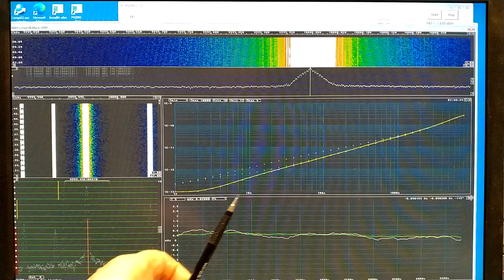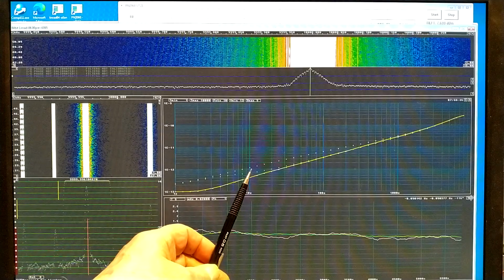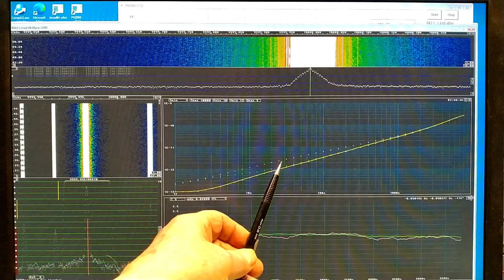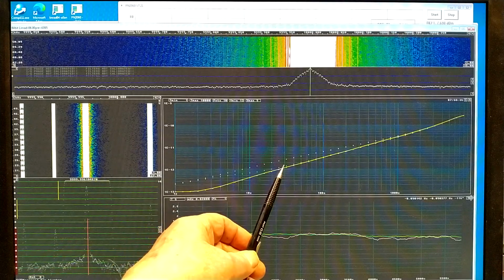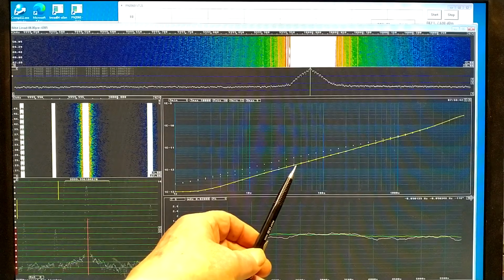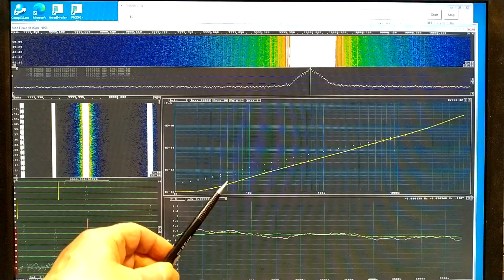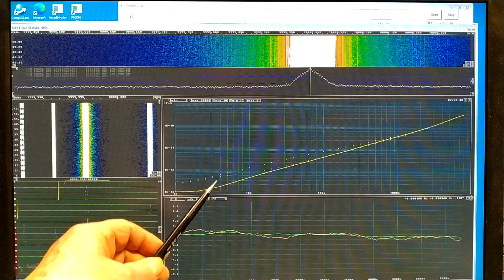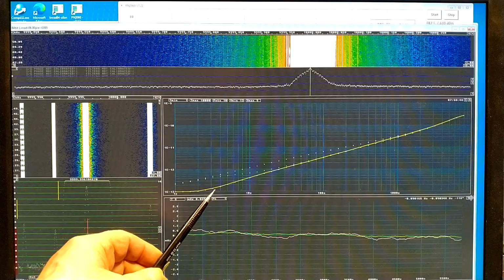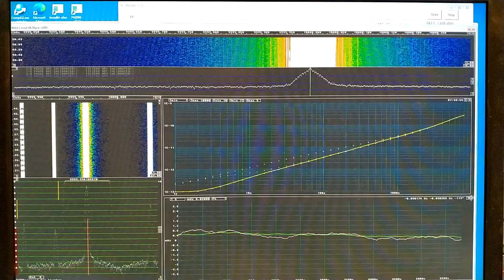And that is very clear from the Allan graph also. You can see the red points are high above the green ones. The yellow line is the correlation between these two curves, and it goes far below both of them at times below 10 seconds. So it is obvious I have a problem with temperature.